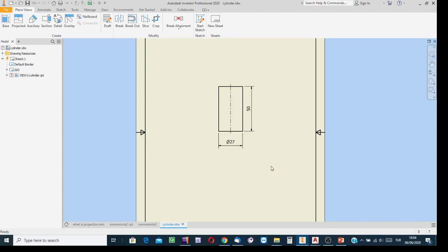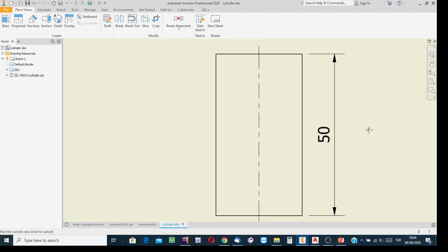What I am doing, you see, is passing through the stages of reading. First, I perceive the quadrant and say that it is the front side view, and then, what is the geometry? In answering this question, there are actually two hints on this view. The main hint is the longitudinal axis. As the figure, we have a rectangle, but on the rectangle we have a long dash, short dash line.